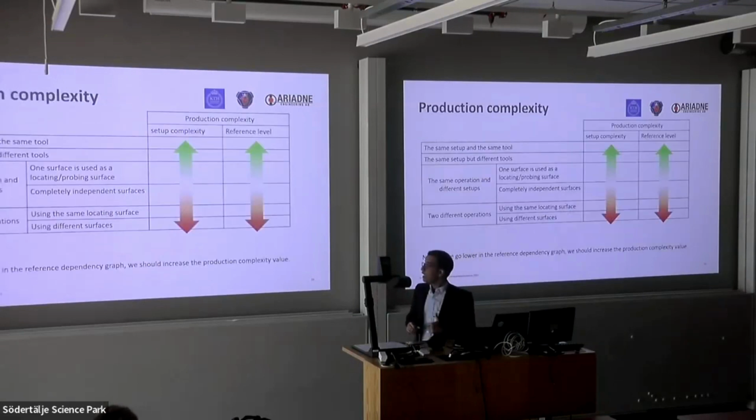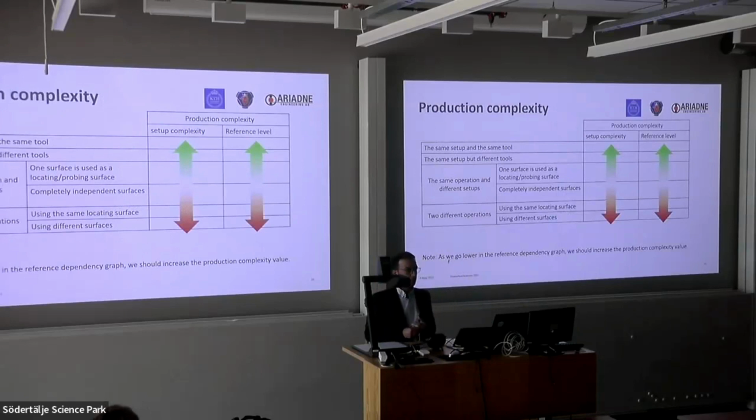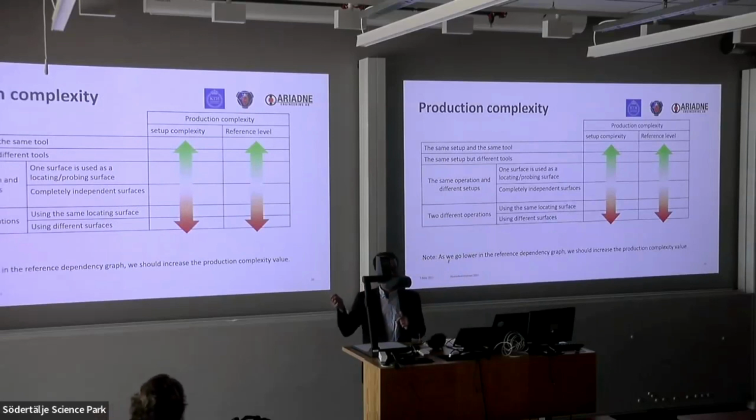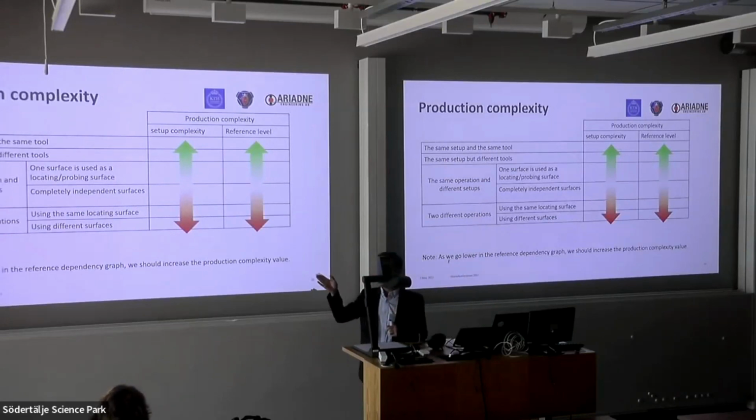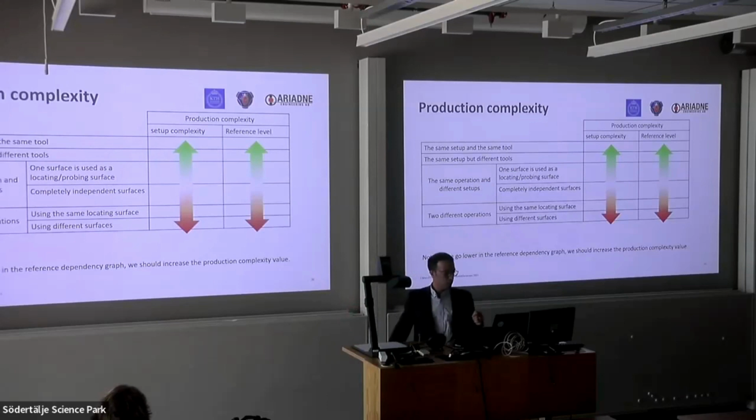And then we have a setup complexity in production. In the best case, you can reach a good result when you are producing a feature and its reference in the same setup and using the same tool. But when you use different tools, or you are producing it in different setups, then you will get a worse result.